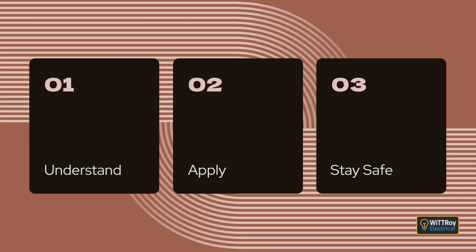Clause 3.3.2.9 Presence of flora. Where plants or vegetation could create a hazard, the wiring must be chosen or protected so it remains safe. This may mean using a different wiring method or adding extra protective measures.